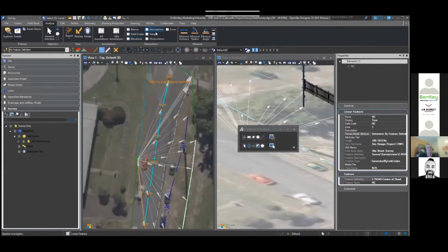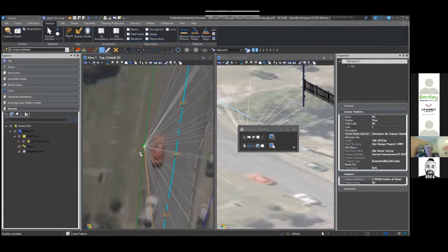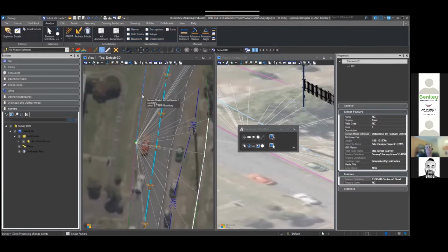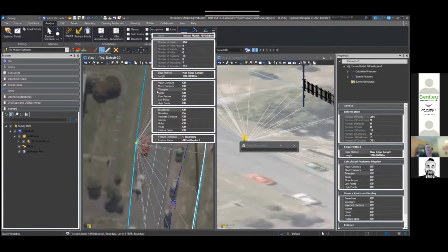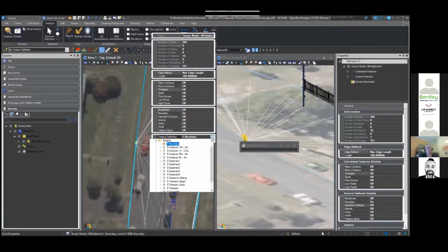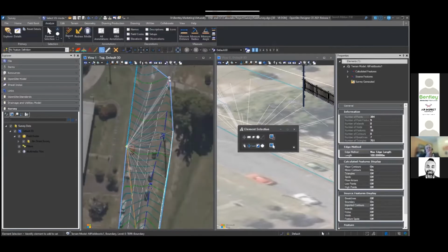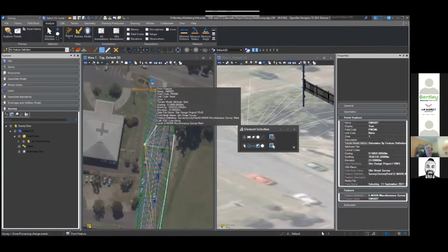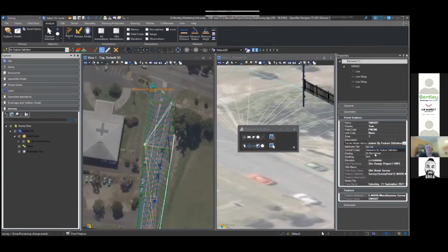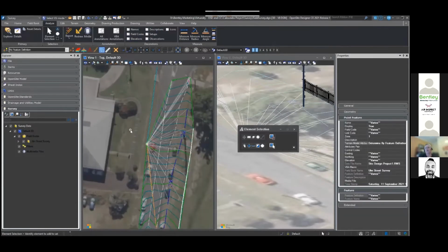Now, in addition to mapping the observations and the features, it also dynamically creates a terrain model. At this point in time, this terrain model incorporates the control points, which is really outside the scope of the survey. I'm really focused on the center line of Ulm Street eastward. Therefore, I don't want to include those points within my terrain model or my tin. So I'm changing the properties to do not include, to clean that up, and dynamically the terrain model updates as we make those modifications.